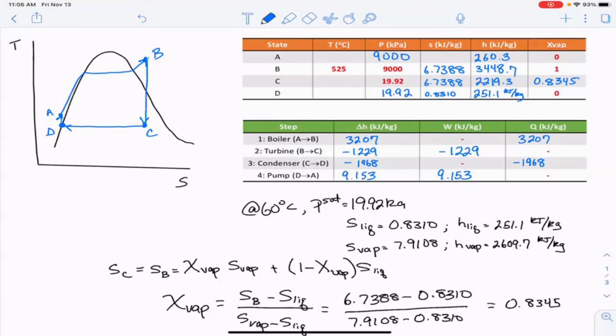But the condition at C doesn't really have any bearing over the condition at D. D is a design point, and whether you choose to make it saturated or subcooled just a little bit just depends on what it is you're trying to do. So that, even though that defines the heat that has to be removed, where you end up at C doesn't have any influence over D. Okay, gotcha. Okay. Thank you. Yeah, good question. All right.